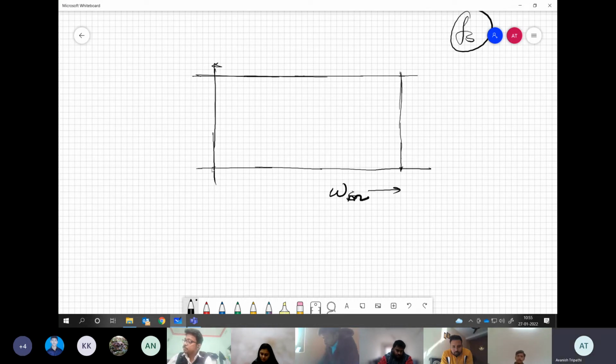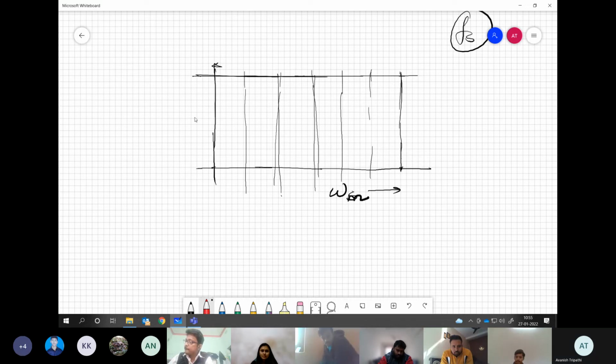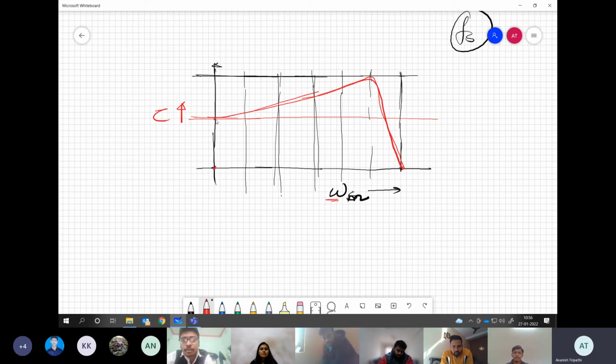So a little bit different manner I will draw than what I have been drawing so far. When you have different frequencies of operation, say this is your natural characteristic. Please mind that this is omega m, not the slip. So at 0 you have the starting torque. Now when we shift, this is the synchronous speed corresponding to say Fs1. Now we have another speed of operation. So this will be the synchronous speed corresponding to that.